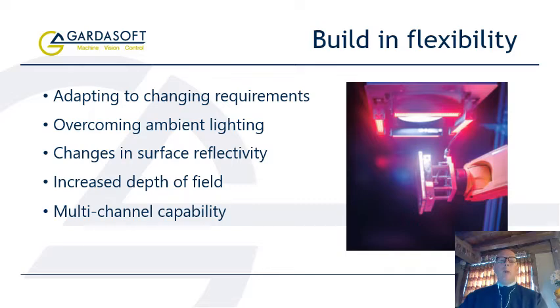For example, inspections may be required on batches of products of different sizes. Overdriving allows the depth of field to be increased by using higher f-stop lens settings, while maintaining image brightnesses by increasing light intensity above 100%. And I demonstrated this with a few slides earlier.